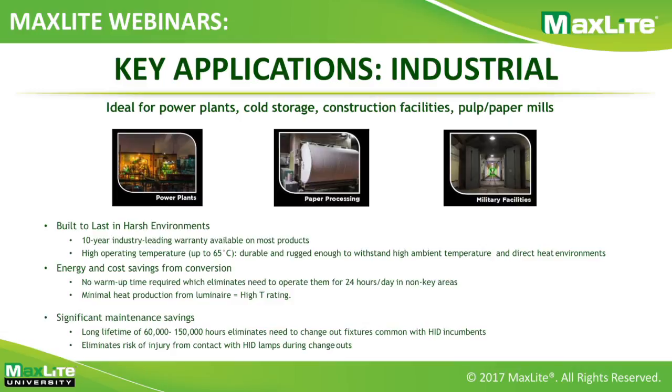This industry will often start looking a little bit more at energy and cost savings from conversion, but when you start taking a look at using hazardous location LED fixtures rather than traditional incumbent options, remember that there's no warm-up time required, which eliminates the need to operate them for 24 hours a day in non-key areas, which is often the case for facilities that are not completely Class 1 and Division rated. A lot of areas, such as cold storage, might only need Class and Division rated fixtures in certain areas of their facility.